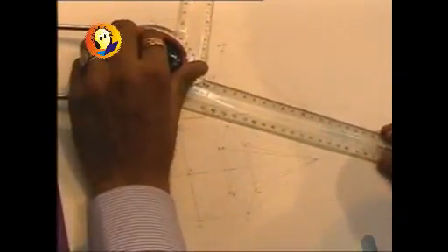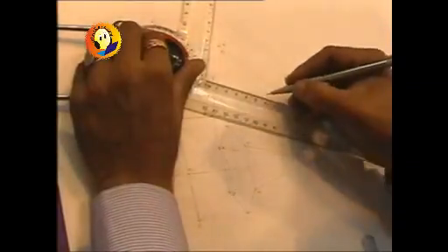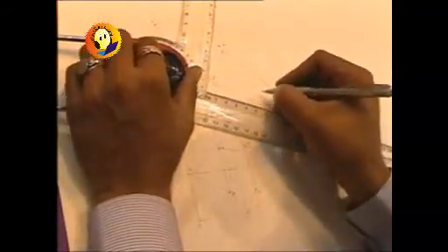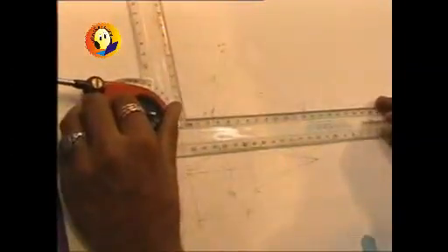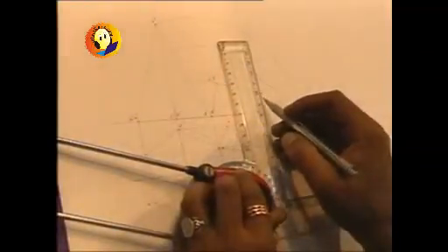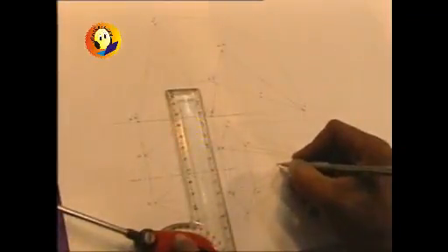Now as we complete the top view, it is said further in the problem that the auxiliary vertical plane which makes 30 degrees with VP passes through the midpoint of the axis. Now the axis over here is overlapped by CF and is seen in true length in the front view. So let us mark the midpoint of the axis in the elevation. That will be the midpoint of CF over here, at a distance equal to 45. Let us name it as point M dash, and then we are required to bring that point to the top view, because the auxiliary vertical plane will be seen as a line in the plan. So draw a projector through M dash and get point M on the axis in the top view.